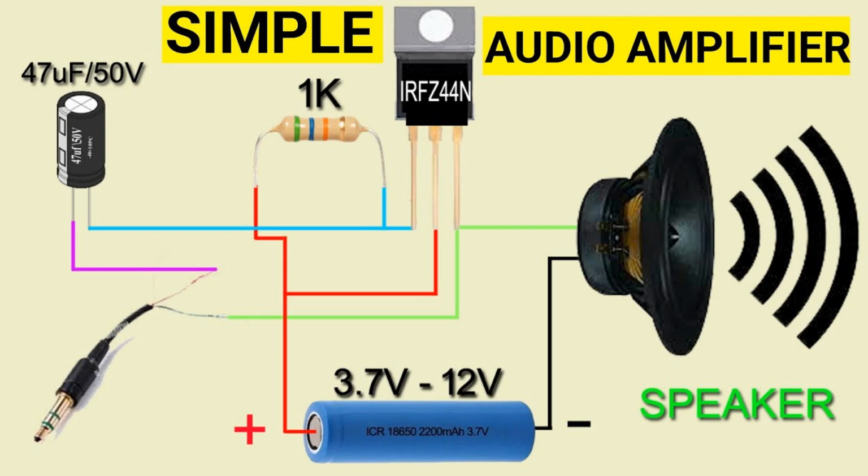Voltage control mechanism. Threshold voltage, VTH. The threshold voltage is the minimum gate-source voltage required to create a conductive channel between the drain and source. By varying the gate voltage above this threshold, the MOSFET controls the channel conductivity and, consequently, the current and voltage.